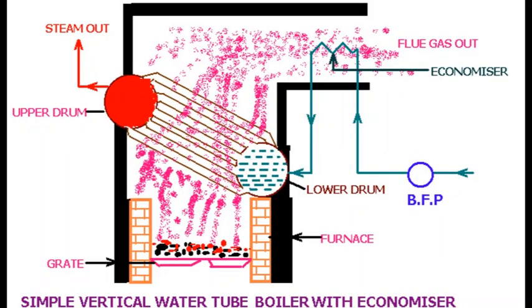In view of the losses observed with the flue gas, and considering the arrangement required for minimizing these losses and to get more heating of the water within the system, the feed water line has been diverted from the boiler feed pump through the waste flue gas duct.